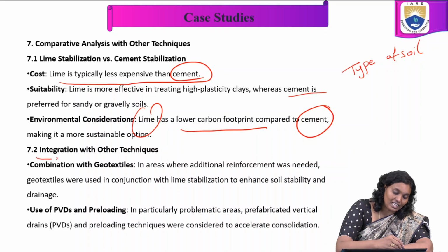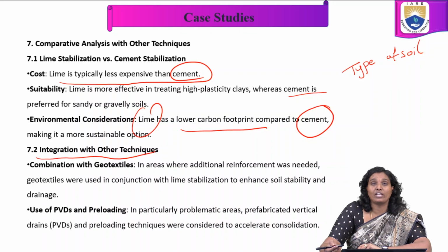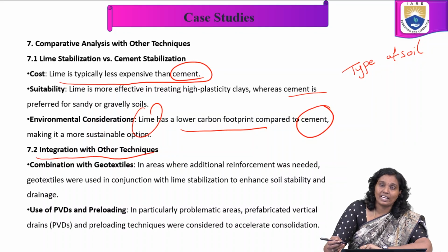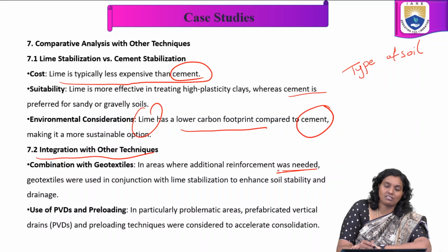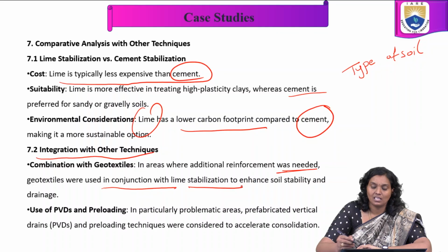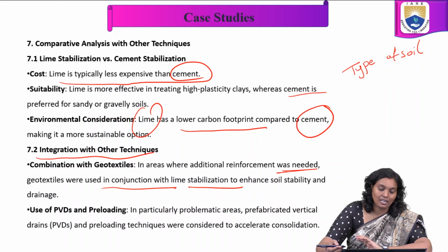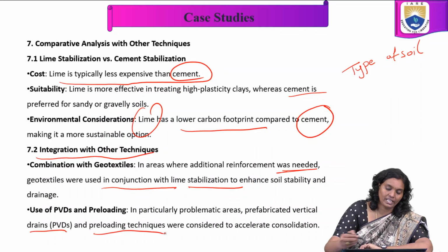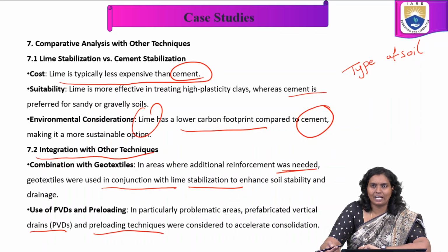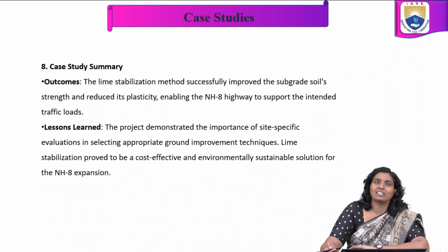In integration with other techniques, combination with geotextiles: in areas where additional reinforcement is needed, geotextiles were used in conjunction with lime stabilization to enhance soil stability and drainage. Use of PVDs and preloading: in particularly problematic areas, prefabricated vertical drains and preloading techniques were considered to accelerate consolidation. So these are the comparative analysis with other techniques.